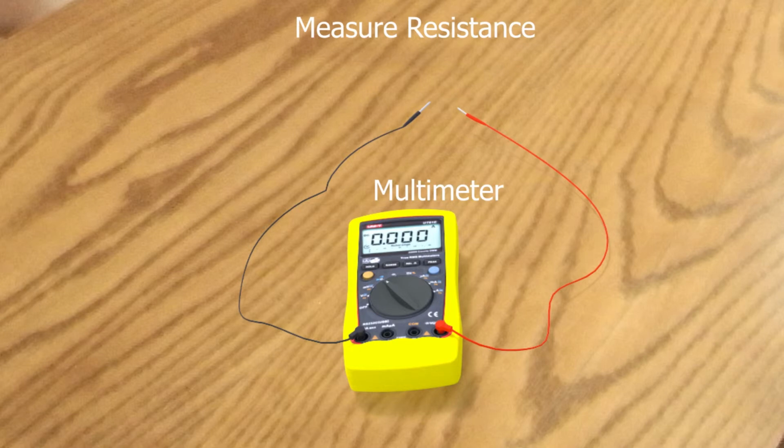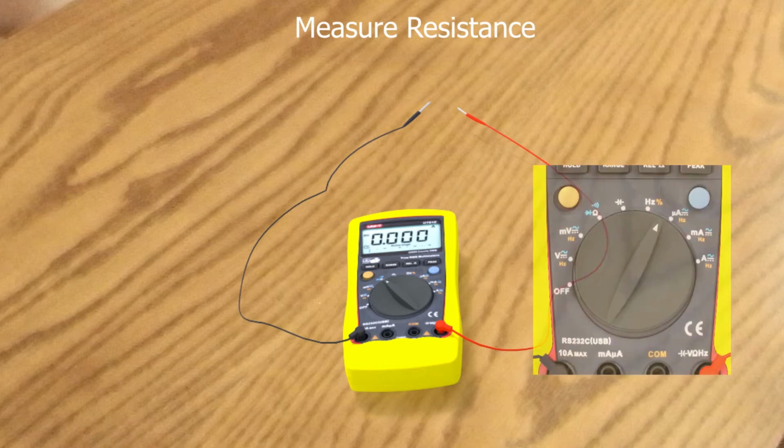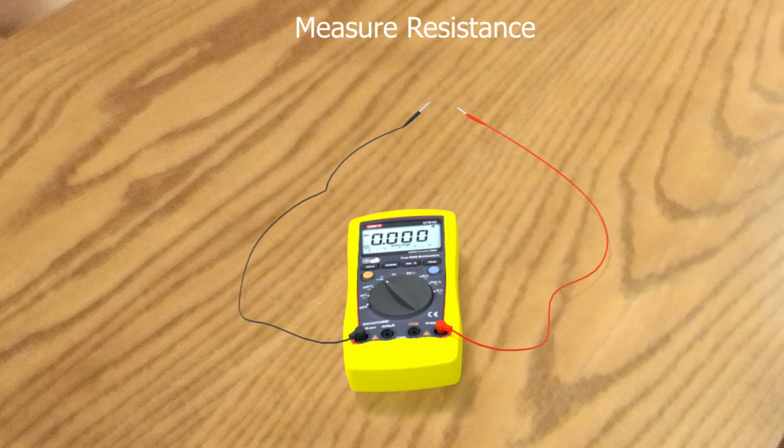Steps for resistance measurement: turn the face dial to the position for the required resistance measurement, then touch both terminals of the multimeter together, and adjust the meter range to 0 ohms. Touch both terminals of the meter to a resistance and take the reading.